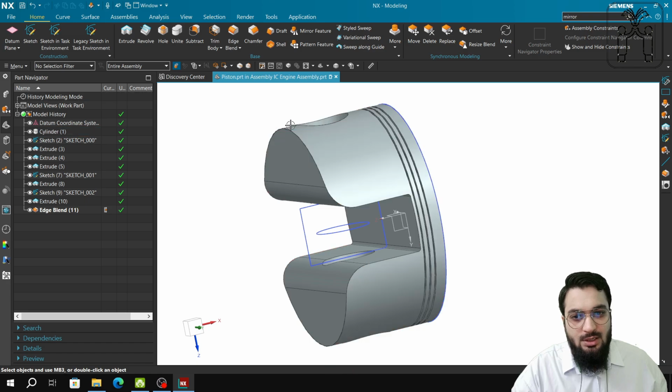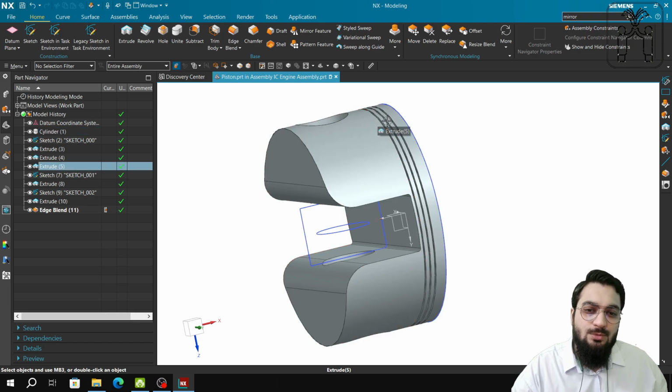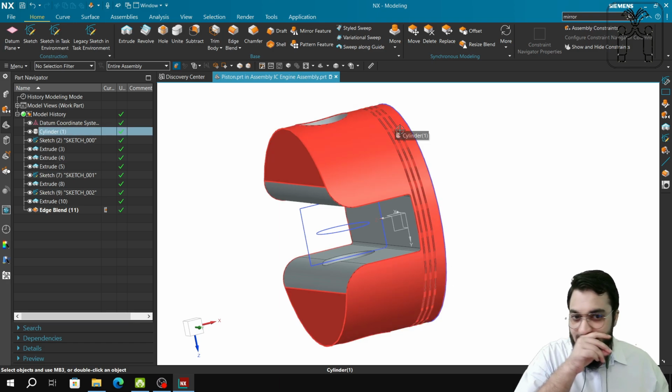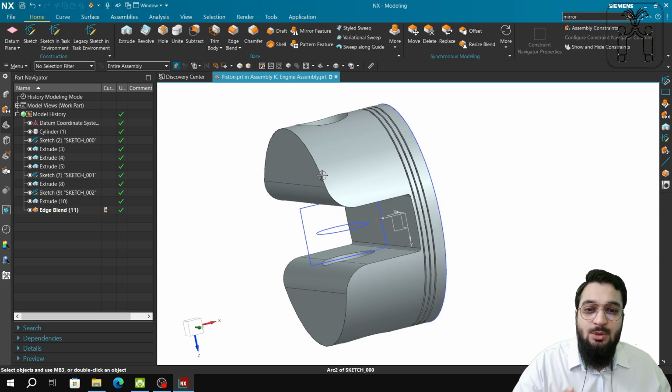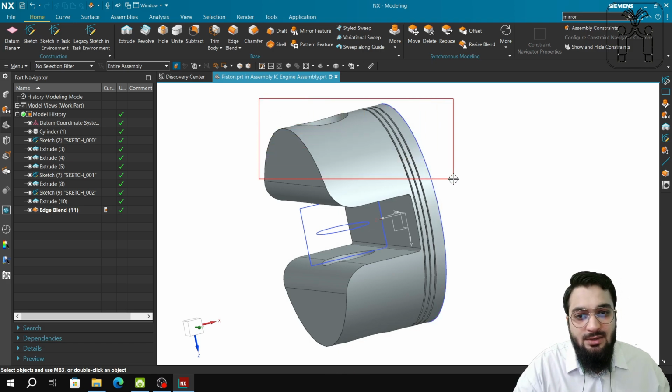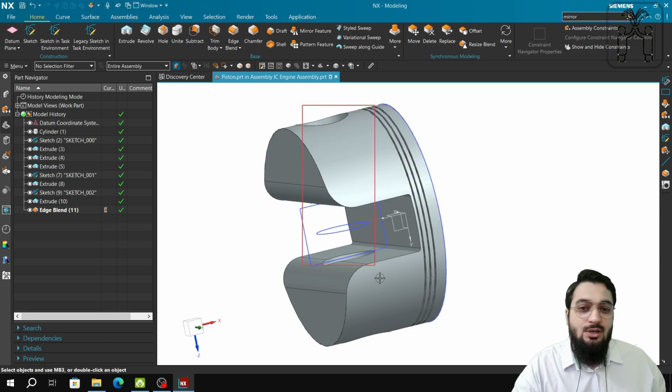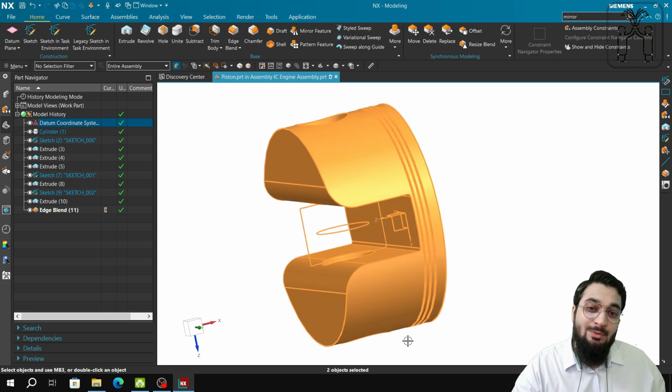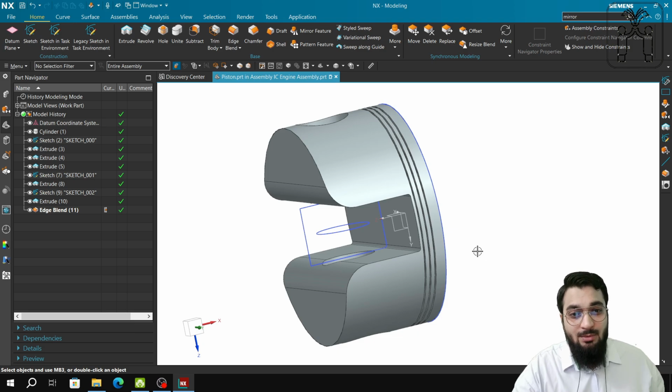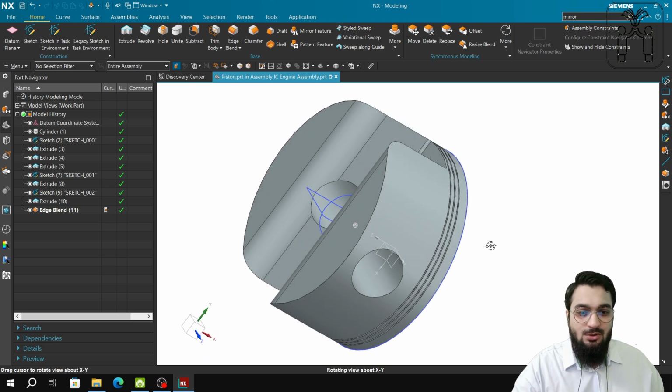Here it was 20 mm, here 5 mm, here 5 mm and something, and here we have to make 3 grooves for the piston seal rings. We will find out why we make those too. The total length is 40 mm, and the total of this is 80 mm. To be noted, it is 80 mm, not 81 mm, even though the connecting pin is 81 mm. It is not 81 mm. Why? We will get into that also.